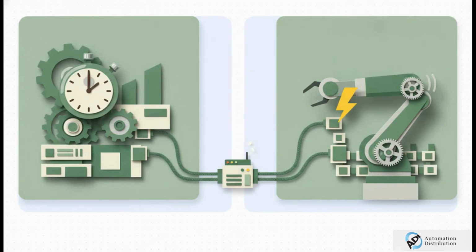Now, let's say you cross the pond, or you open up a European-built motion cell. Boom, you are stepping into Siemens territory. This is where PROFINET's strict timing and GSDML files absolutely rule the roost. If you fire up your laptop and launch TIA Portal, you're in PROFINET country. Now, the big thing you need to watch out for here is the timing. PROFINET RT handles your standard cyclic I/O with soft real-time. But if you're dealing with coordinated motion, like robotic arms or really high-speed synchronization, you're looking at PROFINET IRT. That stands for isochronous real-time, and it delivers hard deterministic timing. It's incredibly fast, but man, it is unforgiving and has very specific network expectations.